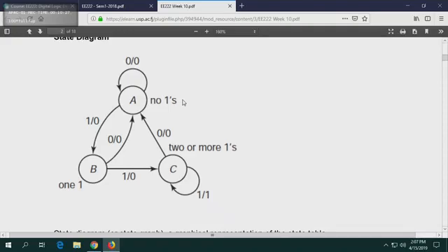If you're given a circuit and you're asked to come up with a state diagram, that's an analysis problem. Analysis means you want to find the behavior of that circuit. When you analyze the circuit, you want to know, if the input is so many volts, what is the output? Or if your input is sinusoidal, what is the gain and so forth? You are given a circuit, you're required to find out what the output will be. That's analysis. So in analysis, your answer is usually two things: the state table and the state diagram. We're going to do that shortly.